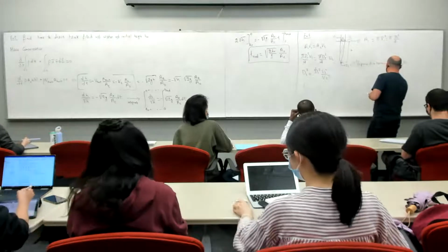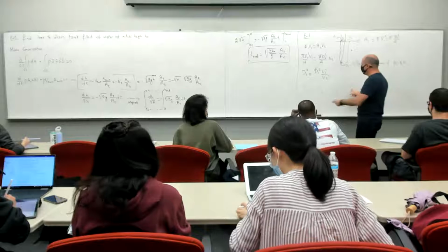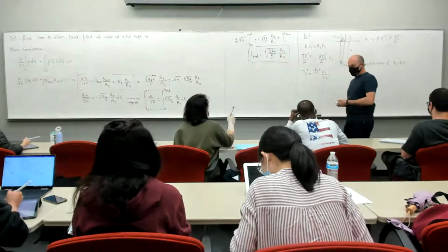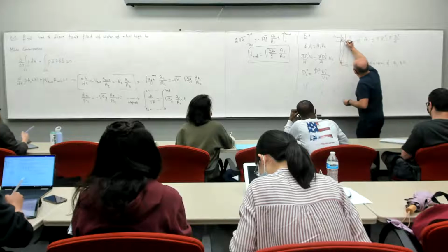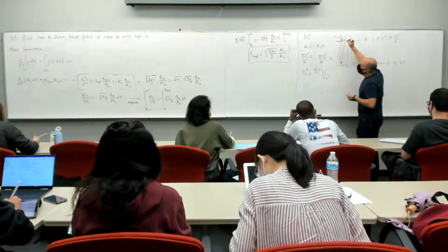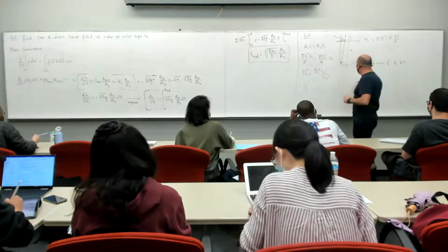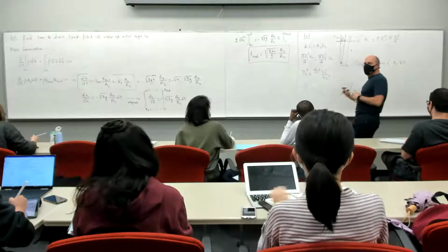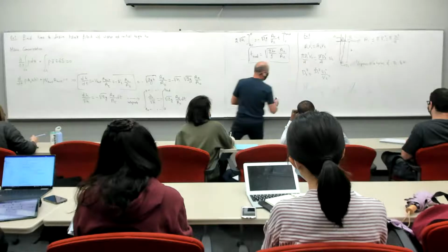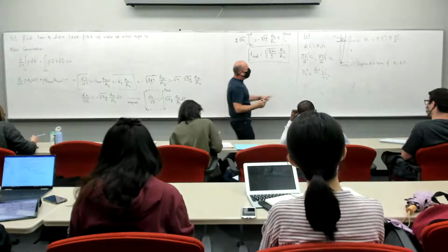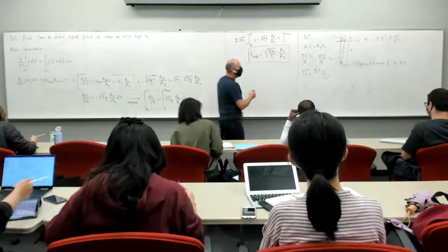Plus GZ2. Okay, so what do you do with the pressures? I cancel that because the pressure equals, because your point is just at the atmospheric pressure, right? That's the biggest assumption you're going to make. Okay, once you do that, remember we're after V2, correct?